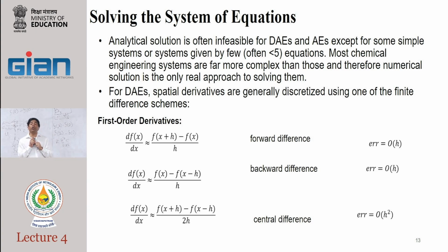So in Aspen, when you solve it, the only thing you would like to solve is the time derivative. Is it not possible to use an integrator here as well as for the time? Yes, you can. It just makes it very, very difficult because there is an inner nesting loop that has to work out. But in Aspen, that's not how it is actually done, and I'll talk about that more. All the spatial derivatives are discretized to convert those derivatives to algebraic models, and the property models are already algebraic. So I will only solve algebraic equations.